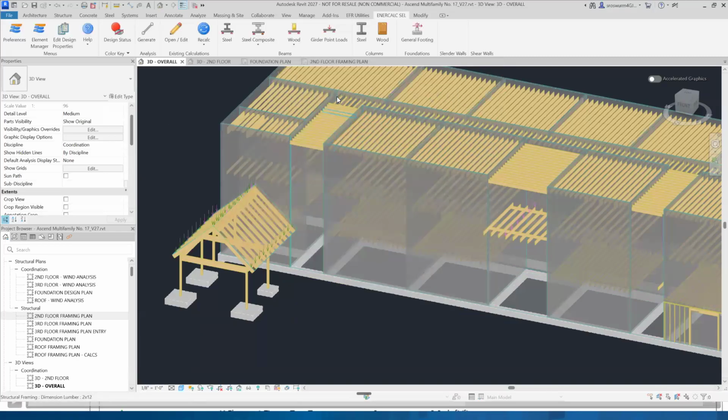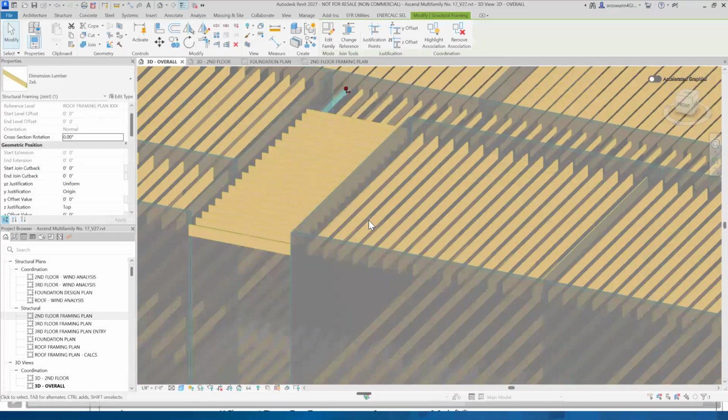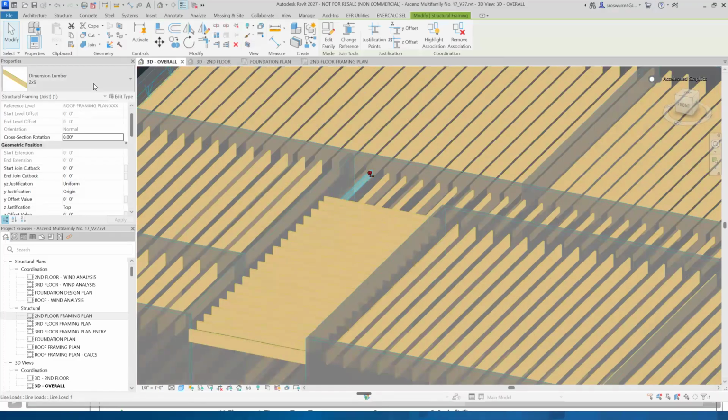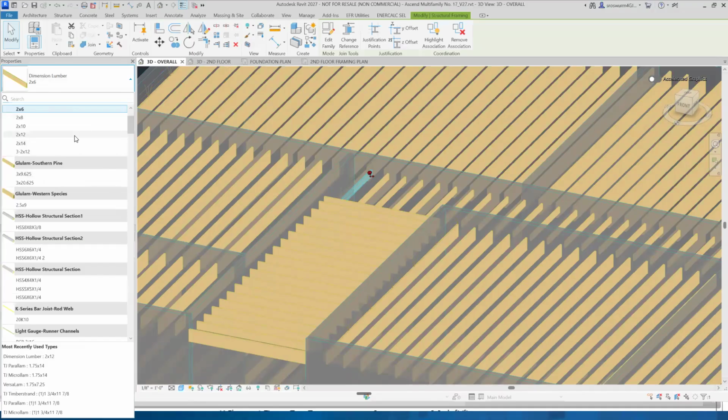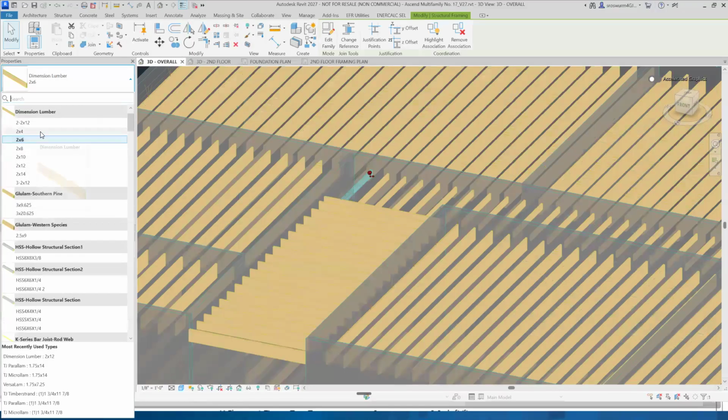So if I were working on resizing one of these rafters, one of these joists, if I've got a 2x6 and all I have in here is 2x4s and 2x6s, say the rest of these weren't in here. If I tell ENERCALC I want a 2 by 12 and I hit save and close, it's a two-step process. ENERCALC for Revit will inspect your project file first and see if the 2 by 12 already exists in the project. If it doesn't, then we use that directory where your loadable content lives and we try to go out and find it.